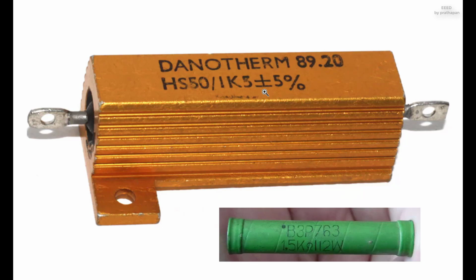A family of discrete resistors is also characterized according to its form factor, that is, the size of the device and the position of its leads, or terminals, which is relevant in the practical manufacturing of circuits using them. Practical resistors are also specified as having a maximum power rating which must exceed the anticipated power dissipation of that resistor in a particular circuit. This is mainly of concern in power electronics applications. Resistors with higher power ratings are physically larger and may require heat sinks.